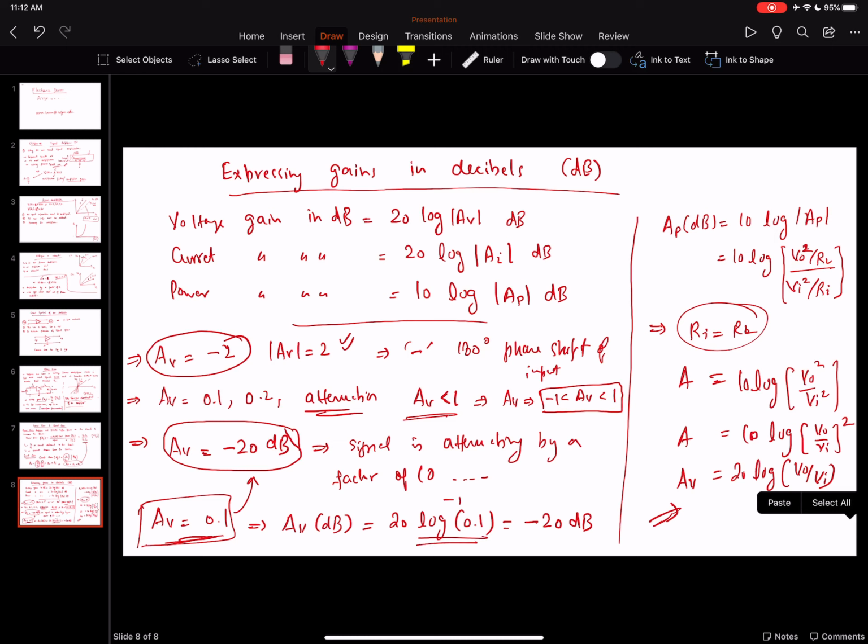So if you see a voltage gain as an absolute value, not in dB, then the negative sign means it is inverted, 180 degrees out of phase. However, if you see it in decibels like this, it means your signal is being attenuated. I hope this explanation has made this concept clearer, because such questions may appear in exams and quizzes.